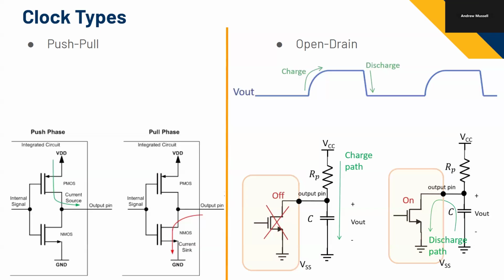Yeah, Jared. What are some trade-offs between the two? Yeah, so like I said, we have a resistor in here that's charging the capacitor. So there'll be some power dissipated by the resistor. So you have to cost more power. Because you have the RC charging, that's going to take longer than a constant current source. So it'll be slightly slower.